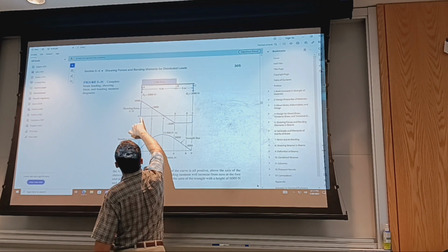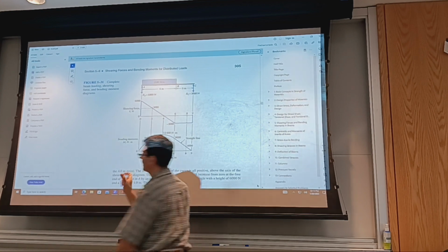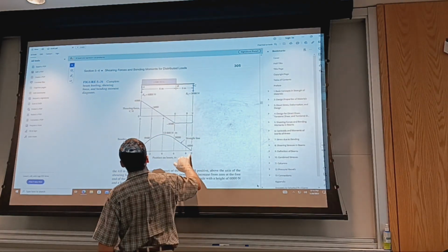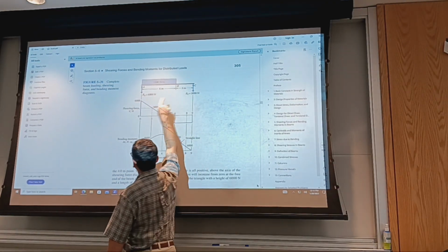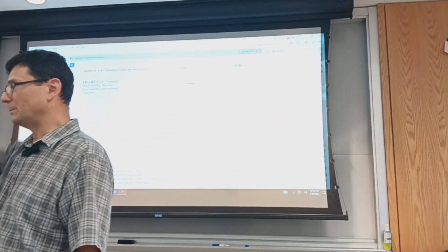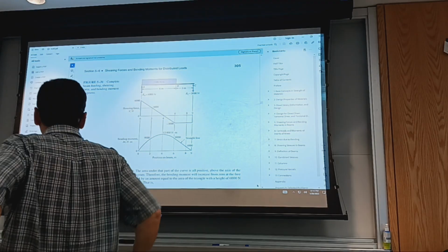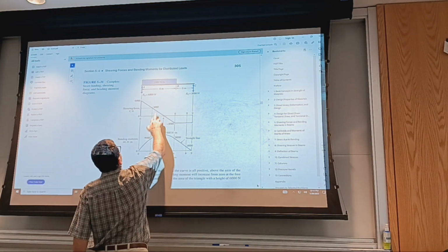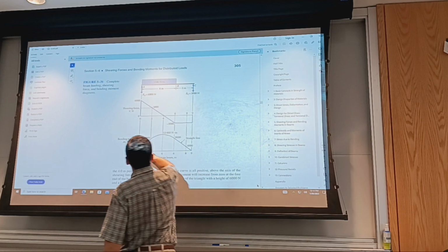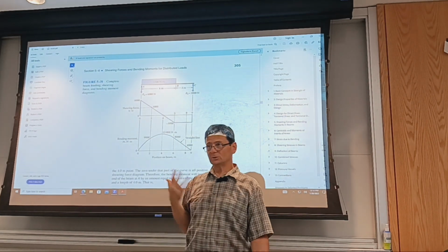If the shear diagram is zero value, then the moment is constant. So it goes to a parabola. And we'll see examples where the distributed load is tapered, linear, not constant. The shear diagram is a parabola, a second degree polynomial, and the moment diagram is a third degree polynomial.